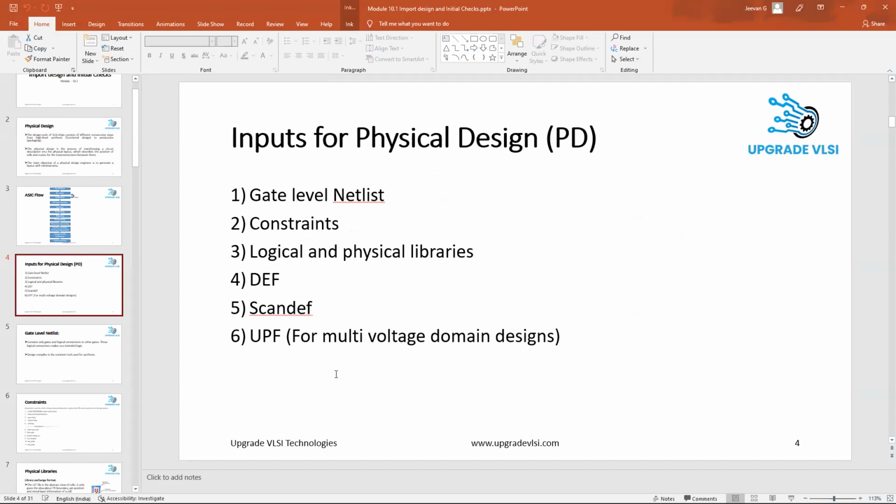As I said, you're going to do some scan chain concept, then you will come to know how much length these cells got spread over the chip or over your partition, and how much time it will take to perform all these things. DFT people will be doing the scan chain method. They're going to test the thing. DFT stands for design for testability, right? They test with the help of this scan chain concept, and that particular scan output we're going to get is called scan DEF.